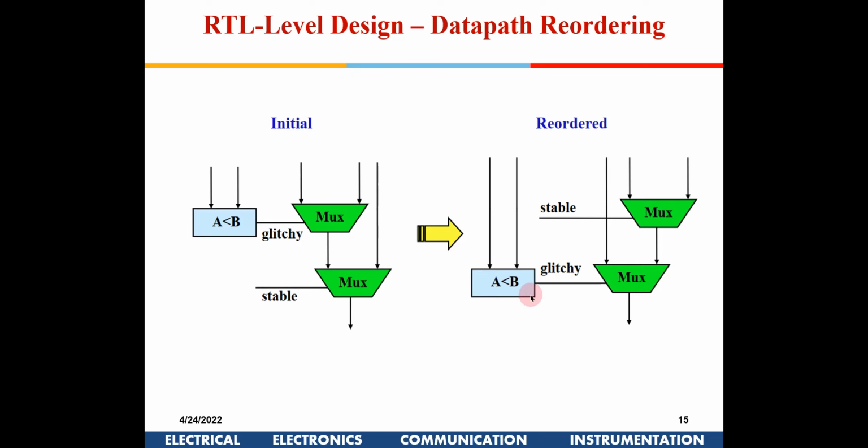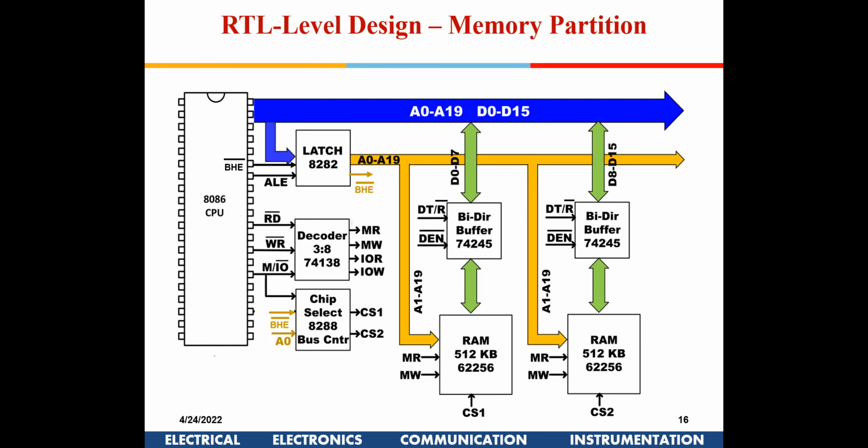affect this mux. So this is again reordering the RTL, and when we do an RTL design, we need to be careful when we are having these muxes and control signals. If you have a control signal which has got a large activity, then you might as well push it towards the end, so that the preceding muxes don't get affected. These are the kinds of things you have to be careful with.